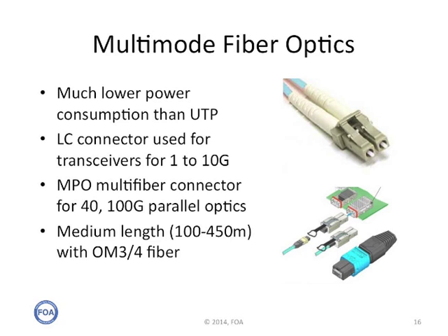Both multimode and single mode fiber typically use LC connectors for single fiber connectors because they are the connectors used in transceivers. Parallel optics for 40 and 100 gig use the MPO connector shown in the bottom of the slide.